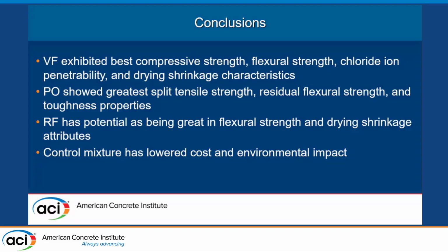And especially because it showed potential, even compared to virgin fibers, to do better in flexural performance and in drying shrinkage. And then overall, the control mixture that we developed, omitting the fibers added, had a lower cost compared to ODOT mixtures, and then the environmental impact was a third.